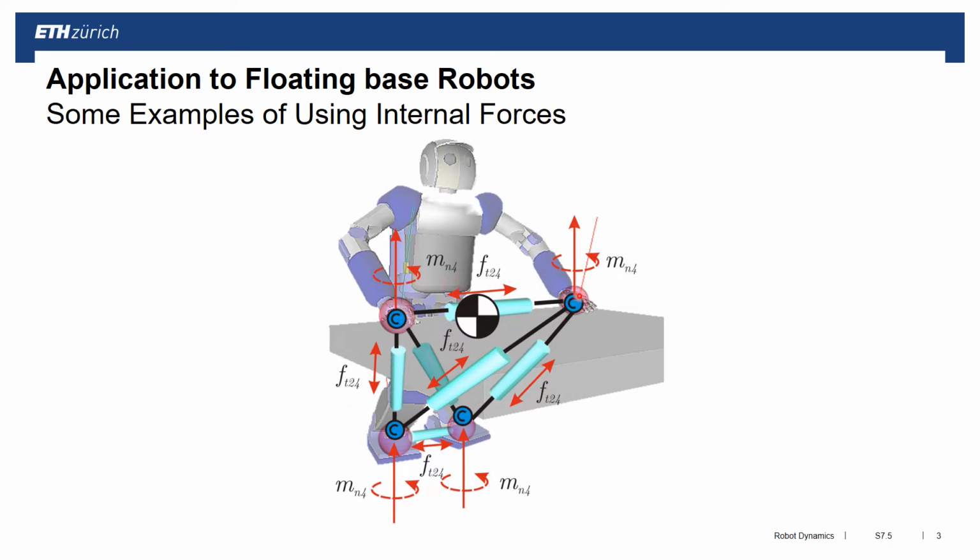By changing these internal forces, we are changing the joint torque distribution, but again, without changing how the system is moving. In other words, we can stand or sit in exactly the same configuration while producing different joint-level torques. One produces more, the other less internal forces. So I can, for example, optimize the way I'm interacting with the environment, producing a certain force at a contact point, or I can optimize for requiring as little torque as possible in the joints to be efficient.